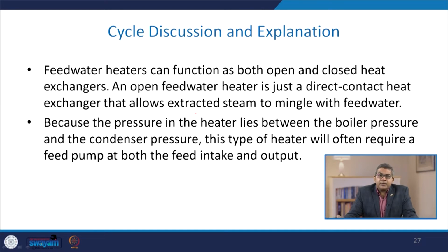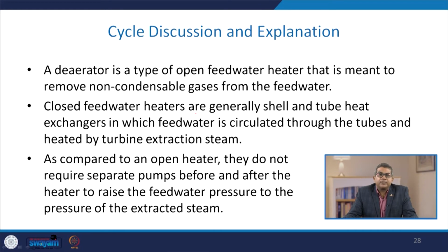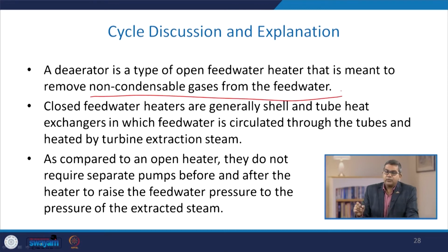Because the pressure in the heater lies between the boiler pressure and the condenser pressure, this type of heater will often require a feed pump at both the feed intake as well as output. A deaerator is a different type of open feed water heater system. This is meant to remove the non-condensable gases from the feed water along with air.